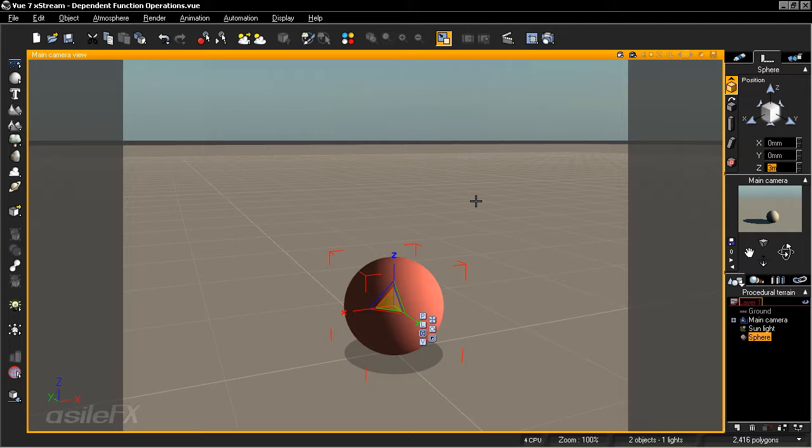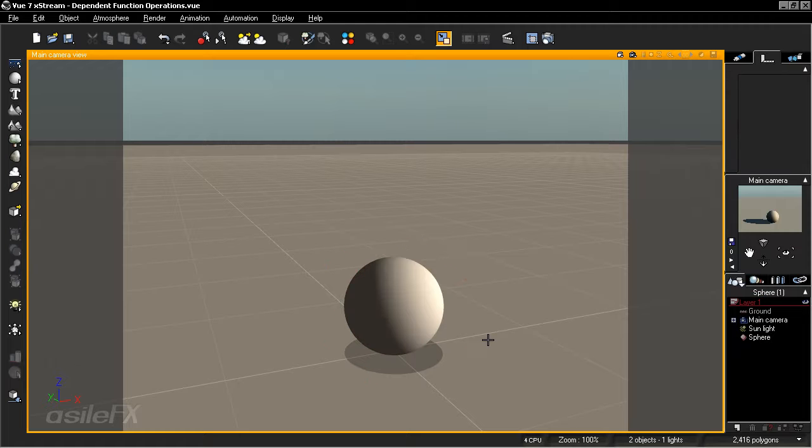If we were to set the internal unit to 1, then the value would stay the same, but the size of our object would be slightly larger, and the position would actually be 30 meters. So we would end up with a vector of 30 representing 30 meters rather than 3 meters. And because of this, it is important to pay attention to our internal unit, because we are going to be using the object's vector output to control those blend ratios and any other extractable slider within the function editor.